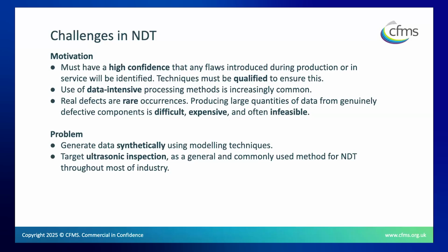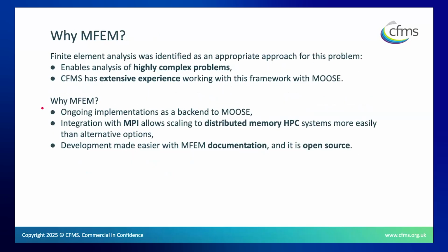We're interested in generating synthetic data, so developing tools to do that, to improve the confidence in testing procedures, and also to provide input to things like machine learning. Specifically, we're targeting ultrasonic testing in this work. So normally that would mean you'd apply a piezoelectric transducer, which would vibrate to produce an elastic signal in the component, and then that would reflect from things like cracks or whatever it is that we're trying to find in the component.